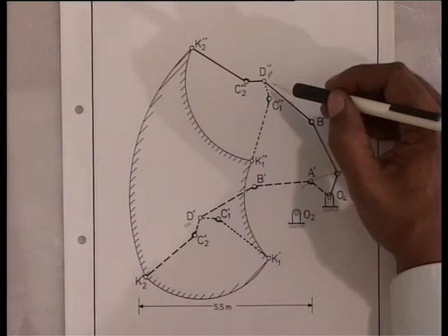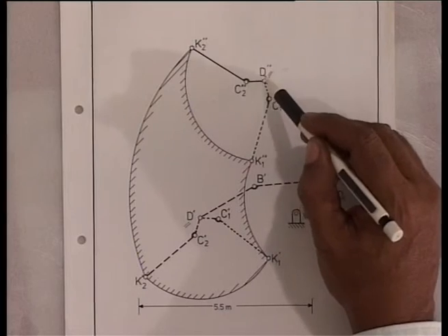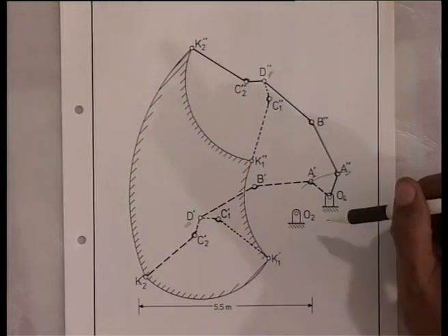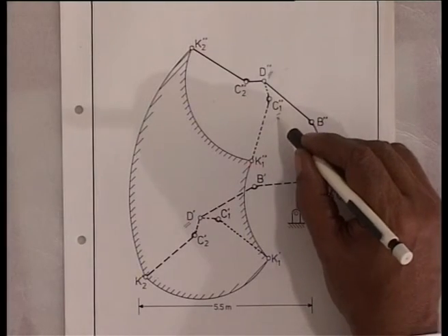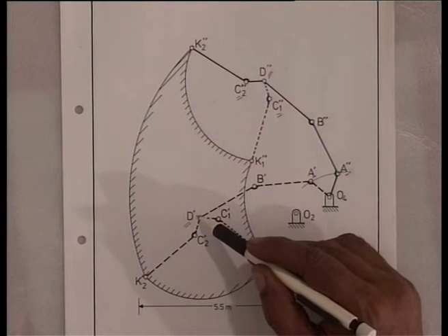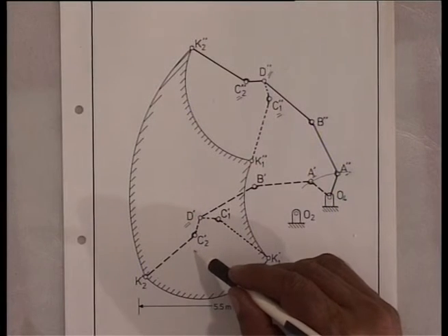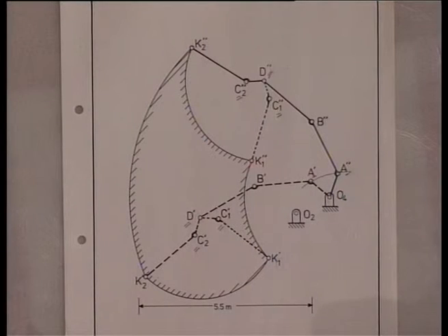So, corresponding to the maximum position of DC and minimum position of DC, depending on the movement of the actuator Z2 corresponding to D2 prime, I get two locations for C. Same way, corresponding to D prime, I get two locations of C, corresponding to the maximum and minimum distance of BC.